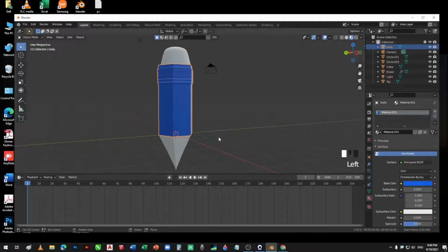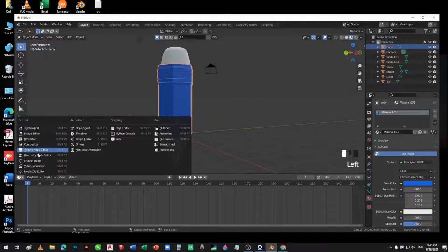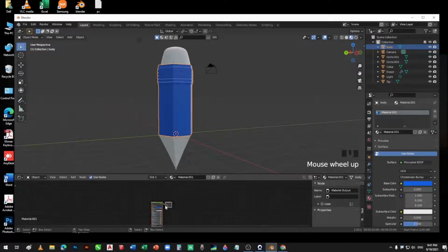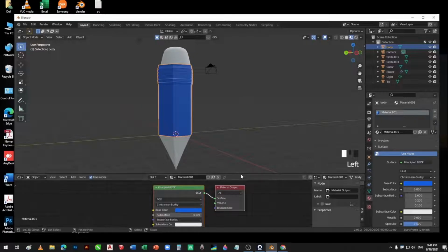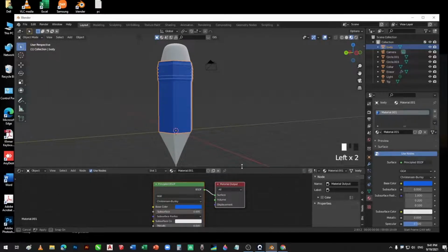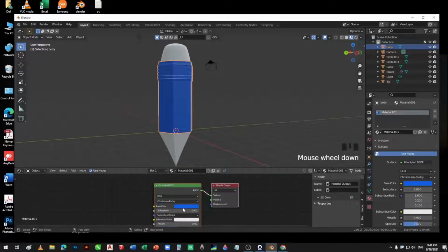If you need more modified color, you could go to the Shader Editor option in the timeline below, by clicking the pop-up arrow on the left side to view it. Then a material window opens with the material base node diagram. Then you could adjust the color on that base color, click and roll up and down.